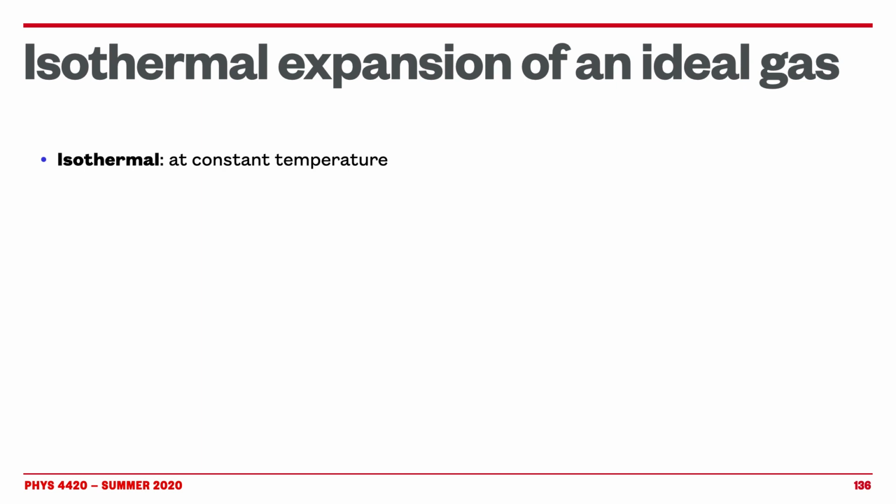Now, this is where things have to be factored in from the previous lectures. If you remember, I kind of insisted on this in particular: if you have an ideal gas, which is what it is about here, the variation in internal energy is the heat capacity at constant volume times dT, the variation in temperature, right? That's what we discussed. So this is an important thing to remember, and please, if you don't, go back to the previous lecture. I believe this is where we did this. Okay. Now, dU equals Cv dT.